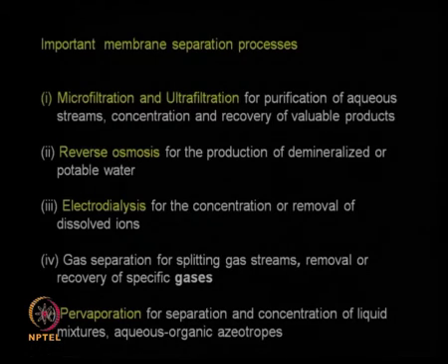Suppose we have ethanol water, I want to concentrate ethanol to 100%, then I can use pervaporation. Normally for ethanol water we cannot purify ethanol to 100% by distillation, because ethanol water forms an azeotrope. So at that azeotrope further purification or removal of water from ethanol is not possible.